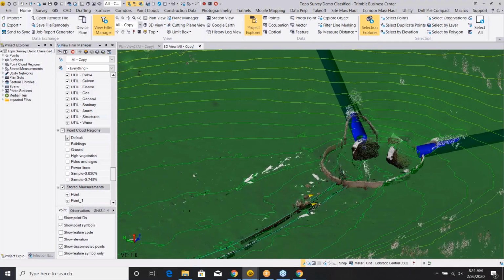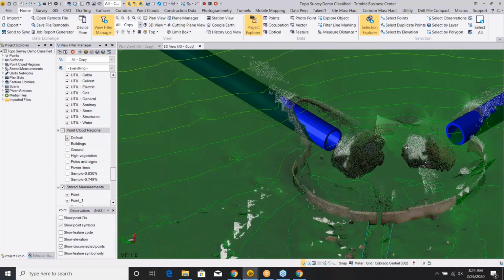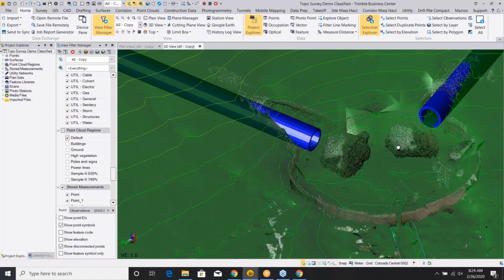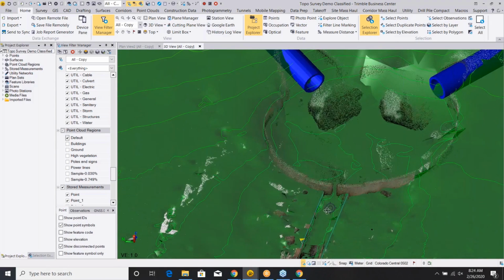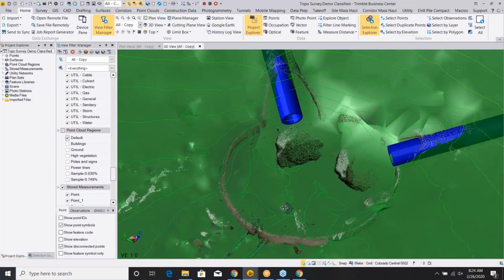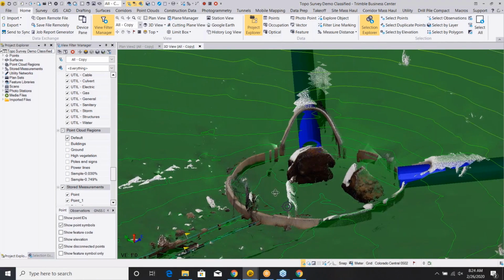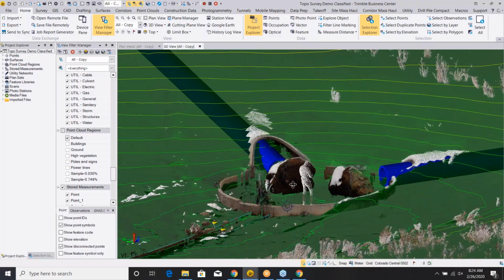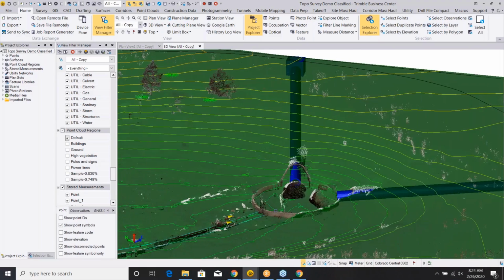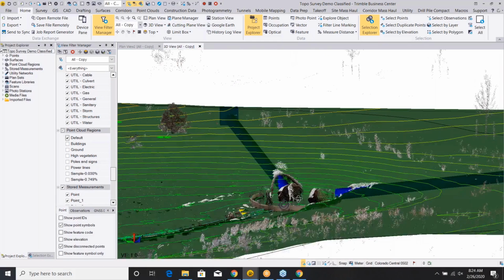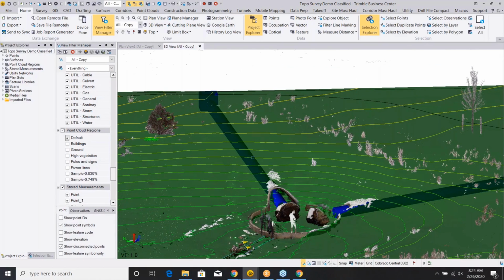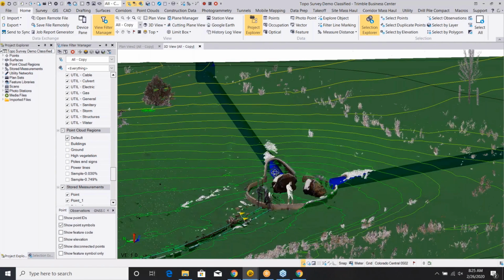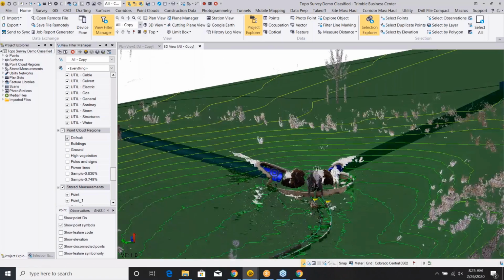So when you export all of this data from the TBC SiteVision AR exporter, you will need to upload all three files to Trimble Connect in the same folder, and assuming they all have the same file name. Because otherwise, if any of those three files aren't there, the model won't show up correctly on Trimble Connect. And another thing you can do as well is, I don't think we are logged in this case, but if you are logged into Trimble Connect through TBC, you can also have the exporter directly upload to your Trimble Connect account as well. Save a few steps here and there.